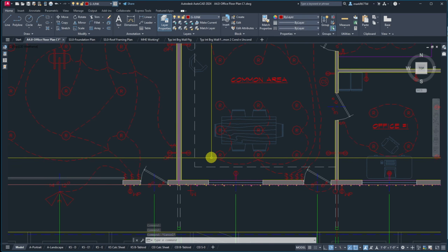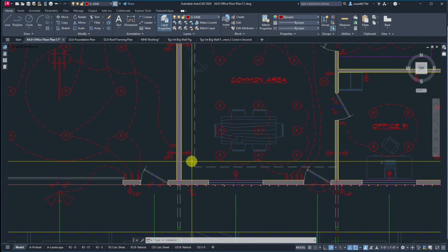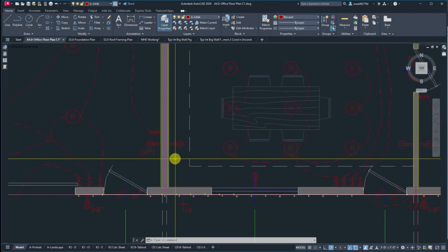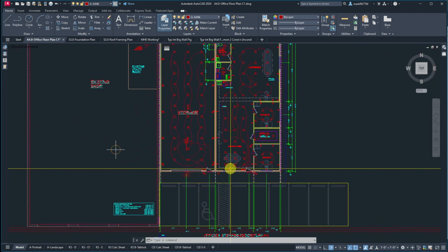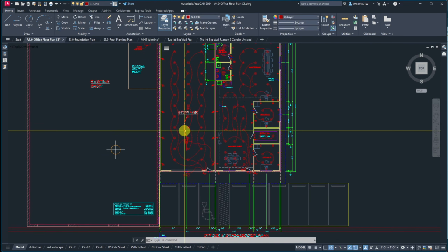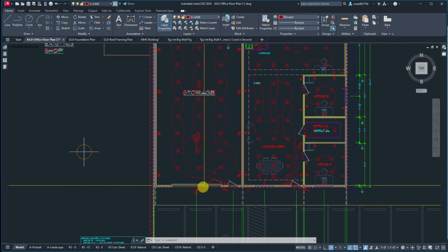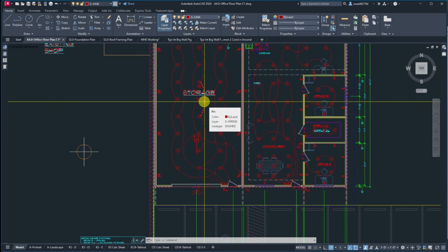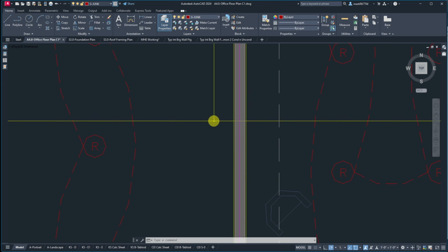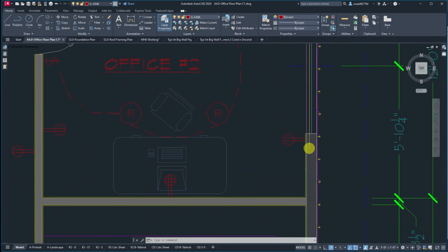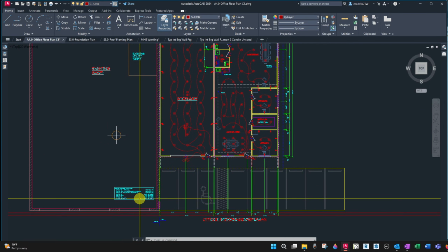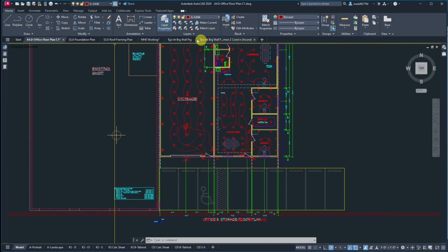But what it kind of symbolizes, if I were to be off 4 feet out here, is that's how I want the insulation, to come down this common wall. Because this room holds offices, conference room, it's heated. This storage area, I don't even have an insulated door. So this whole area is not heated. So we're going to do 1 hour fire protection between these two spaces. And then we're going to insulate this to the same degree we would an exterior wall, which is R21 cavity in Montana. And so let's just change up that detail so I can send out an actual detail.